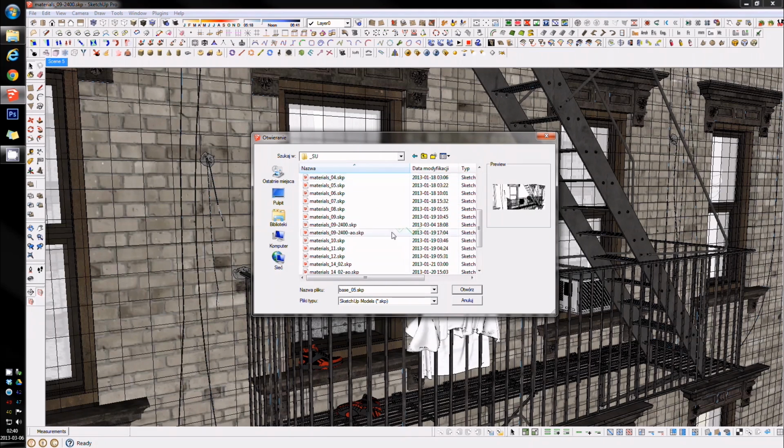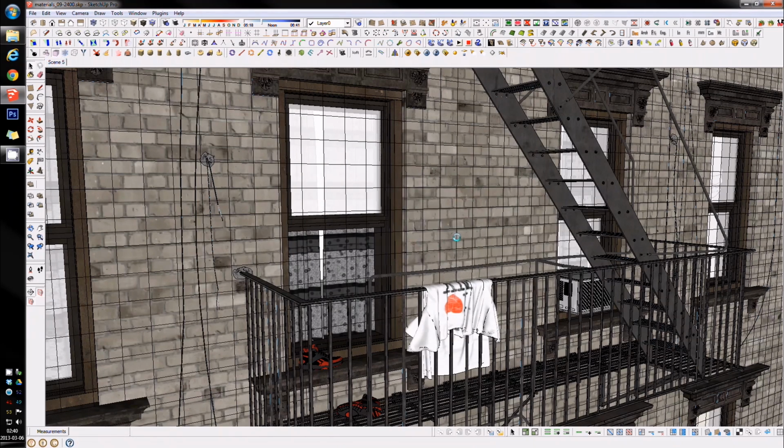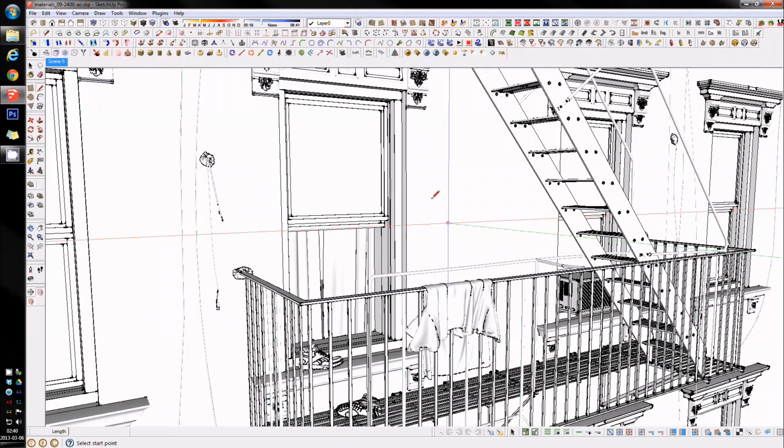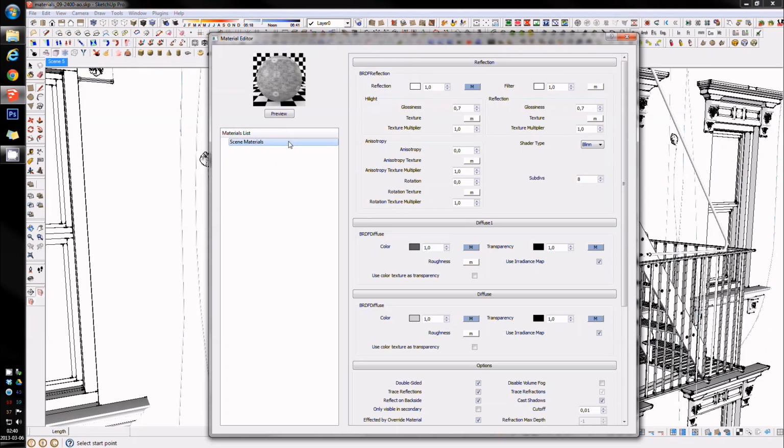Channels were more important for me than the other settings. Mainly thanks to them I was able to adjust the shadows, reflections, colors, and every detail in the raw output of my render. I treat ambient occlusion pass as a channel also. I like to have a few ambient occlusion images, so I rendered it in a few variants of the settings and lighting. I use a copy of the master file to be able to remove materials from the whole scene to speed up parsing time a little.